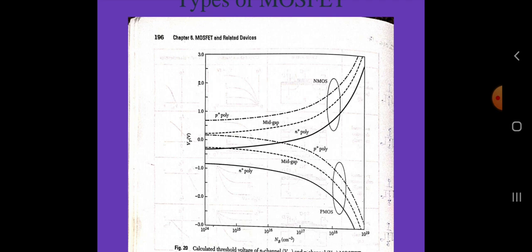Using this method, it is possible to obtain close control of threshold voltage because very precise quantities of impurity can be introduced. The negatively charged boron acceptors increase the doping level of the channel. As a result, V_T increases. Similarly, a shallow boron implant into the P channel MOSFET can reduce V_T.